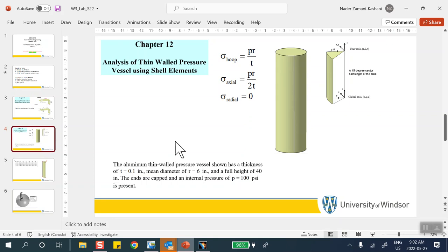Because on the inside you have a pressure. Pressure in the thickness direction is the pressure that you apply, or stress. So what would you say? Is that a fair question to ask in an interview? Okay. The stress is not 0. It's actually the pressure on the inside. And what is it on the outside? What is that stress on the outside? Sigma Z on the outside. What is it? There it is 0.